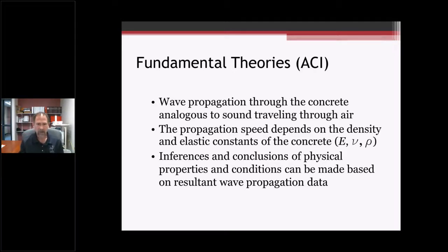And the propagation speed depends on the density and the elastic constants of the concrete. These are Poisson's ratio, density, and modulus values, so the wave speed all depends on those elastic constants within the concrete.